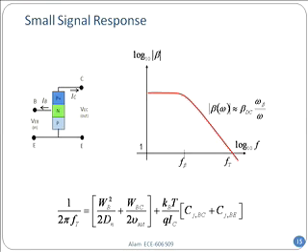There are a bunch of capacitances. Do you see that these are all junction capacitances? Those are also very important on the right hand side. Do you see IC somewhere? Second term in the denominator. If I can forward bias it with a very high IC, then the second term will gradually drop out. And as a result, the whole sum will become smaller, and as a result, I will have a larger FT, right? So for larger FT, I should have as high a current as possible, as low a capacitance as possible, as thin a base as possible, right? So these are the things I want.